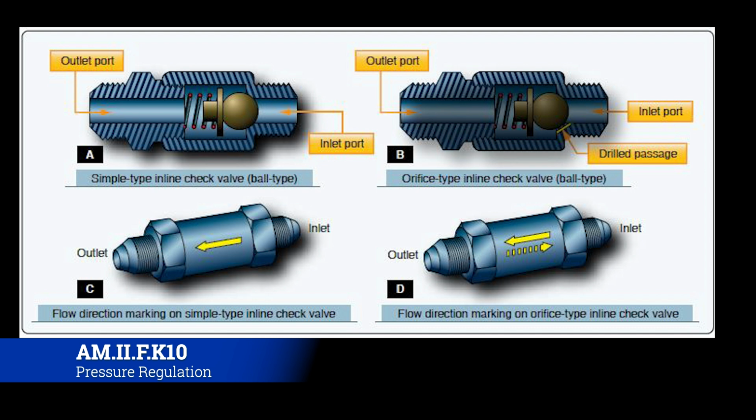Now, whenever the flow reverses and comes back the other way, the exact opposite happens. On the back side of that plate, pressure is applied that seats the valve and seals the line, not allowing any hydraulic fluid to escape back the way that it came. Therefore, making sure that the hydraulic fluid only goes one way.